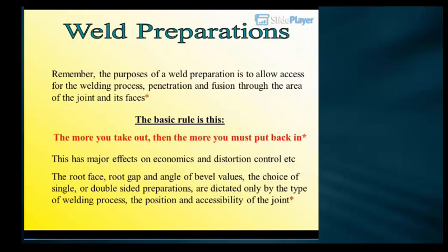The more you take out, then the more you must put back in. Weld preparations. Remember, the purpose of a weld preparation is to allow access for the welding process, penetration and fusion through the area of the joint and its faces. The basic rule is this: the more you take out, then the more you must put back in. This has major effects on economics and distortion control, etc. The root face, root gap and angle of bevel values, the choice of single or double-sided preparations, are dictated only by the type of welding process, the position and accessibility of the joint.